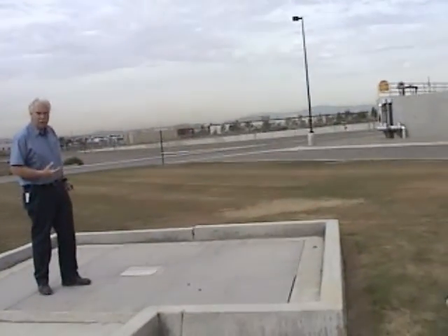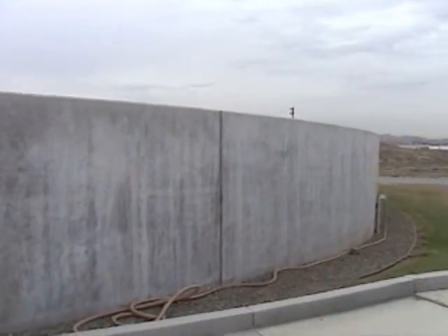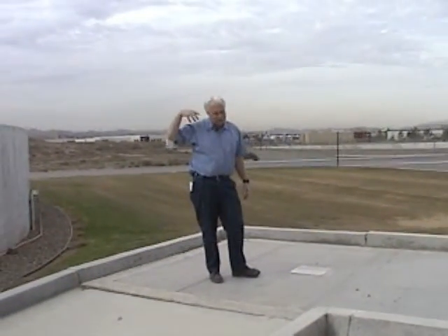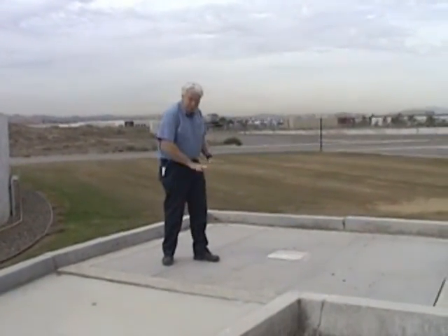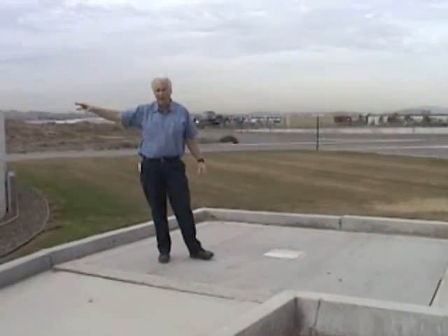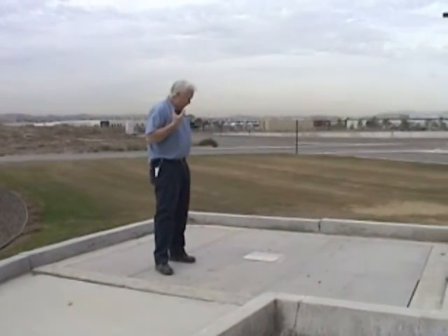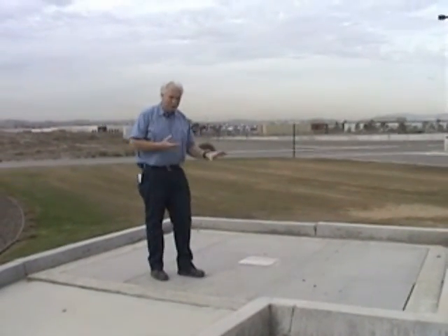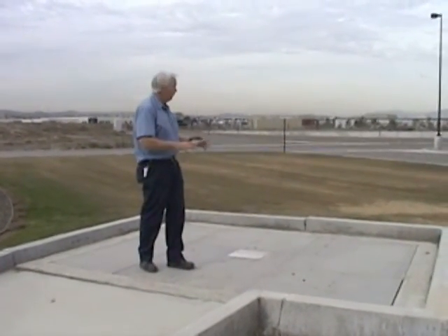What's really important to remember though is because this is very low and the secondary clarifier is full, the liquid level is very high, if that valve is left open and you have a clarifier attached to the other end of it and you're filling that clarifier, it will fill this pit and it will overflow onto the ground due to the difference in elevation. This is really, really important. If you're ever taking a secondary clarifier offline and you're using a pump to pump it out and that pump fails, it will overflow into the street.